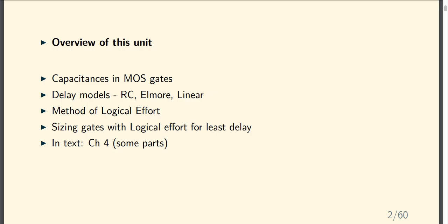And secondly, for primary inputs where we have the connection coming through the pin, in those cases, because of the structure of the pin, which is much larger than the internal connections, wires, etc., there is going to be a more significant inductance. So in those cases, we have to model the inductance. So in general, whenever we are modeling delay at the digital level, for most normal circuits except for ultra high speed circuits, we will call it only the RC delay.